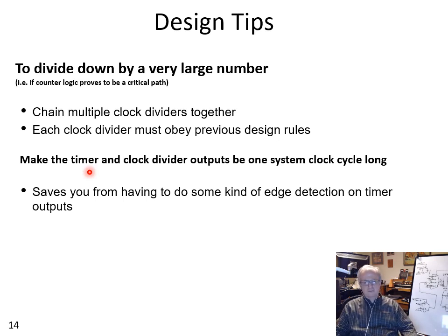A lot of the time that works equally well, but you will occasionally run into situations where you end up needing to do synchronous edge detection on an enable signal to figure out whether, say, to change states. So that's it.